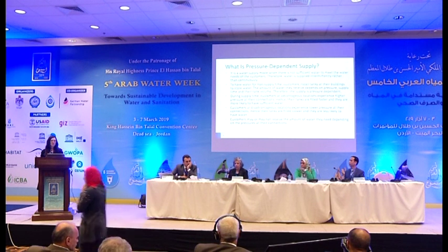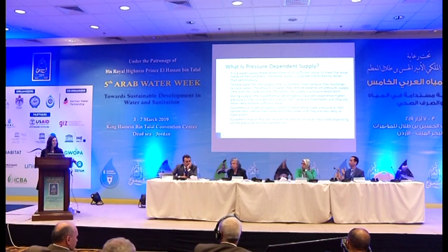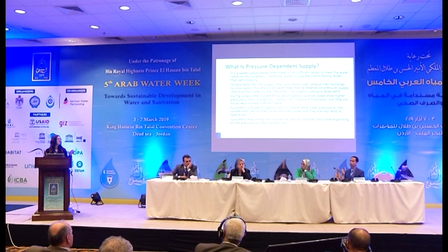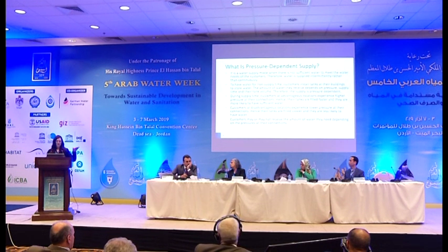But in pressure-dependent supply hydraulic models, we simulate the demand as being correlated to the pressure at the connection point. So when there isn't sufficient pressure at the connection point, customers won't be able to fill their tanks, especially those who live very far from the source or who are in high areas.